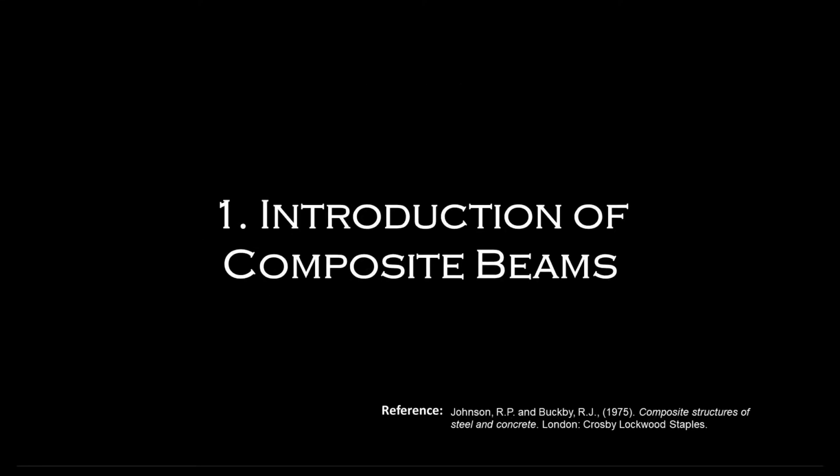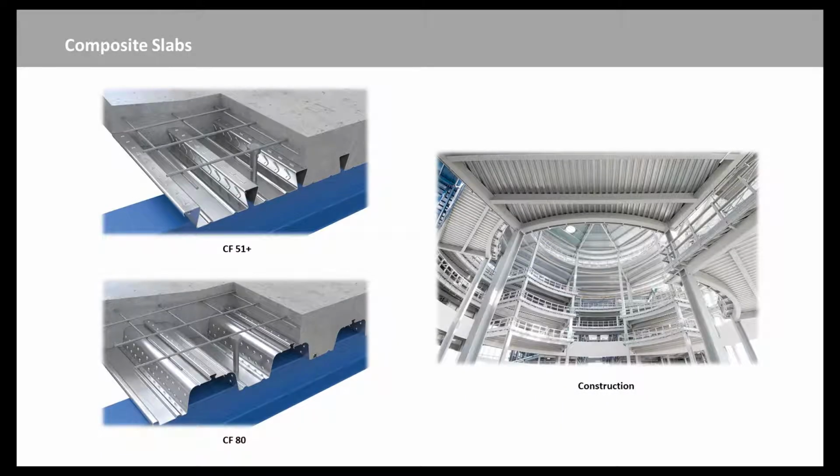Composite beams in buildings are usually supported by joints to steel or composite columns. The cheapest joints have little flexural strength, so it is convenient to design the beams as simply supported. In this video, we will discuss simply supported composite beams.